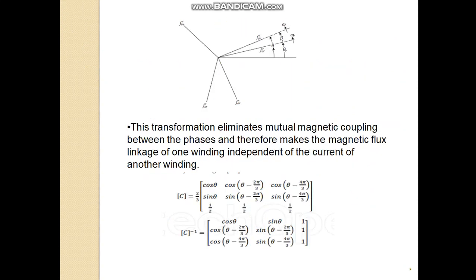The transformation is done by applying a transformation matrix equation, while the inverse transformation matrix will transform back to the natural reference frame. It applies to a three-phase system but can be modified to accommodate a system with any number of phases, which might be useful in the case of a machine having an auxiliary winding, as proposed in this work.